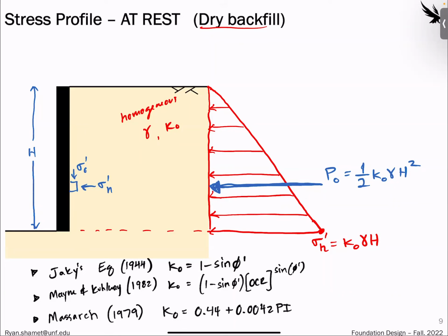So you'll see there's a lot of other equations. These are some of them you can use, but it's always going to be based off of what data you have available. So PI, that's the plasticity index. Remember that one? Remember the Casagrande cup, and how super precise that was. If you're not super comfortable that your Casagrande cup data is really accurate, then you probably should stray away from this equation. Likewise with the friction angles. If you're correlating to find the friction angle, and then you're using a correlation of a correlation, then that can be bad sometimes too. So it's all dependent on how accurate and how confident you are in your data itself.